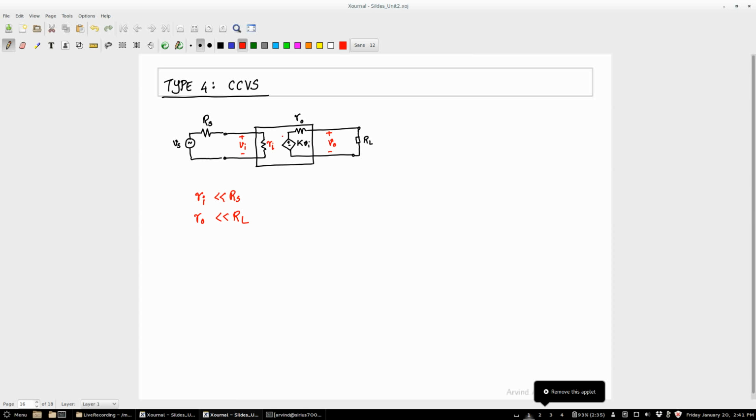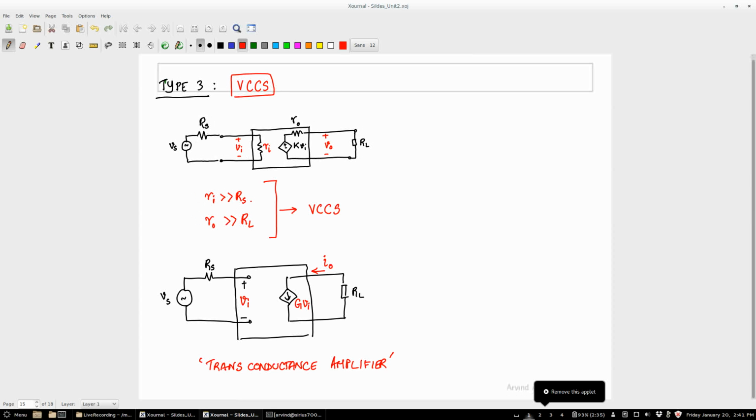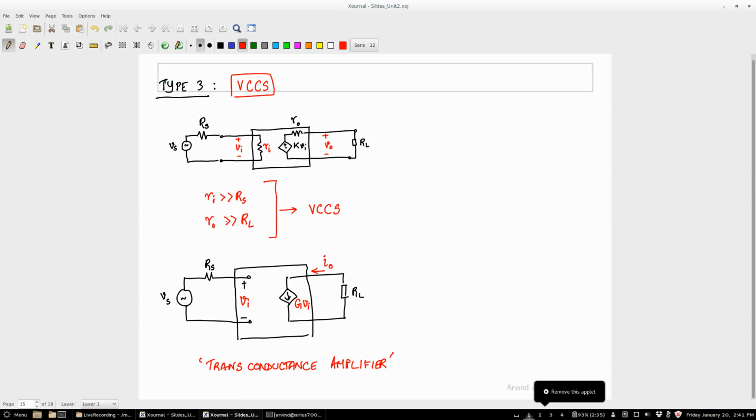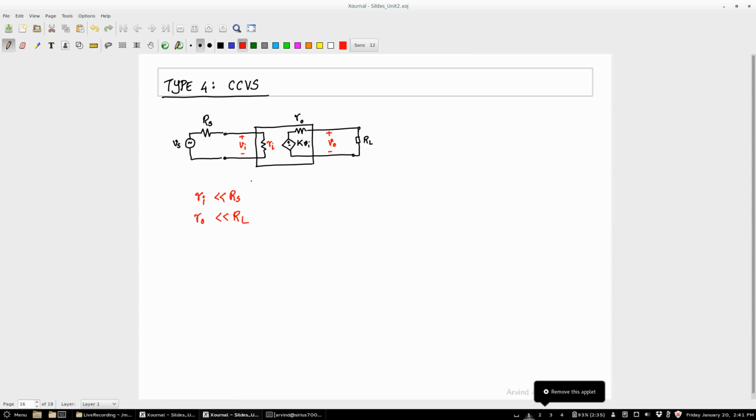So if you take this combination, this dependent voltage, this resistance, you will get a parallel resistance of R, right? In the ideal situation, you don't want any current to flow through the R0, you want all the current to go out, which means that R0 is infinity, right? So which means, no, sorry, I want a voltage source on the output, sorry. So whatever I said, you do it to the input system, right? No, what I've written is correct.